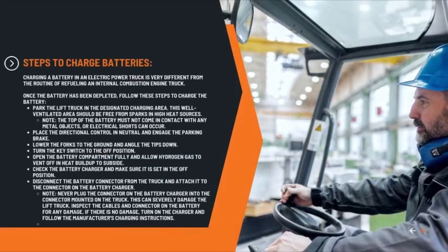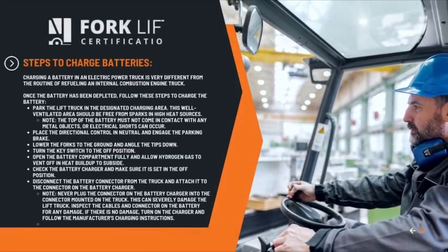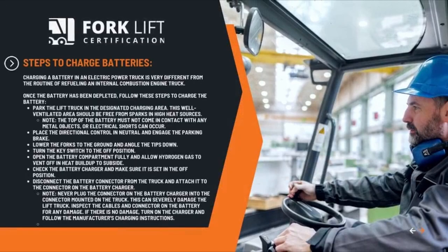Steps to charge batteries. Charging a battery in an electric power truck is very different from the routine of refueling an internal combustion engine truck. Once the battery has been depleted, follow these steps to charge the battery. Park the lift truck in the designated charging area. This well-ventilated area should be free from sparks and high heat sources.